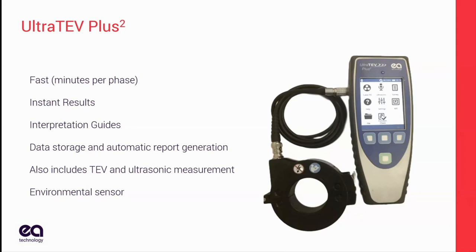It's going to give you phase resolved plots, waveforms, and a variety of algorithms that are going to try to point you toward PD or not. You can record the data and then Wi-Fi it to somebody who's an expert, or you can take a survey, and when you're all done, sit down at the computer and do all your analysis there. So it's a bit more flexible. It does more things. It does one phase at a time, so it takes a bit longer, and you're doing the analysis yourself. So those are the two different product options. They work in tandem depending on what your application is.